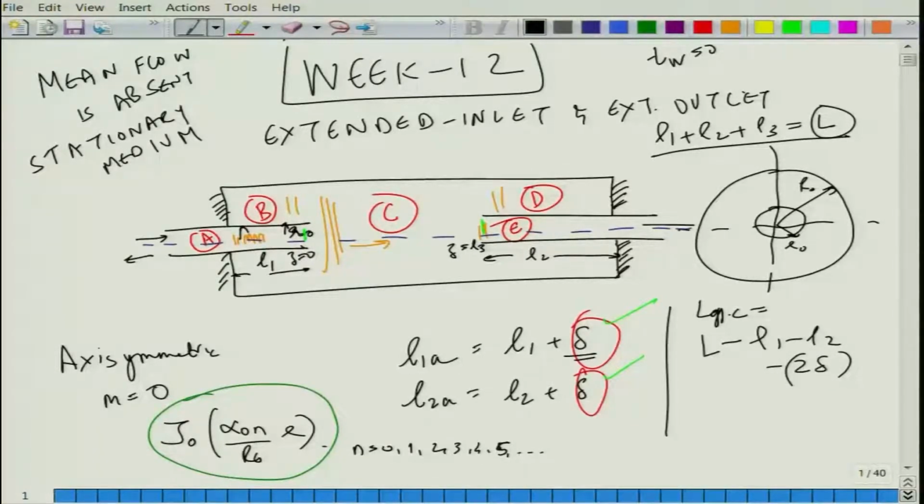But in actual application, you will have certain thickness. So, those effects can be considered in advanced courses, or as more advanced topics. For right now, just for mathematical simplicity, we are ignoring t_w, although some authors like Chaitanya and Munjal have employed finite element formulation taking into account the finite thickness of the wall to get the end correction. So, that they have done.